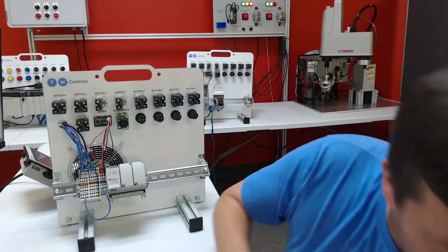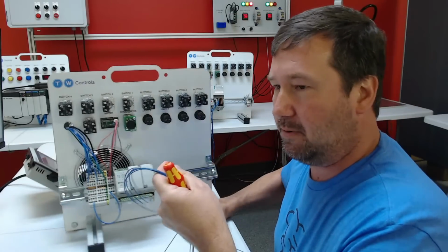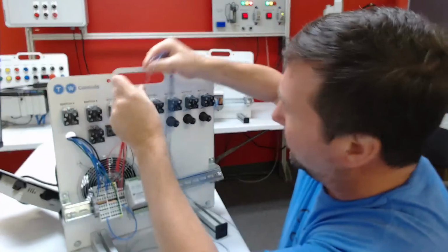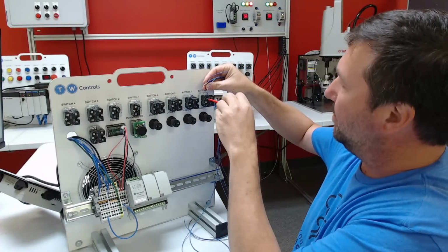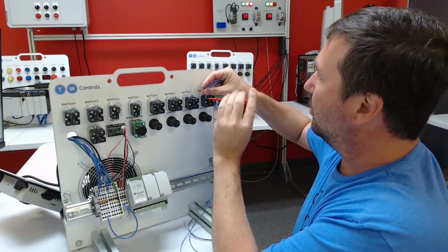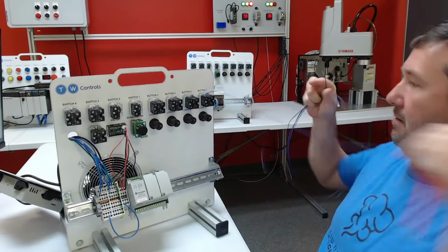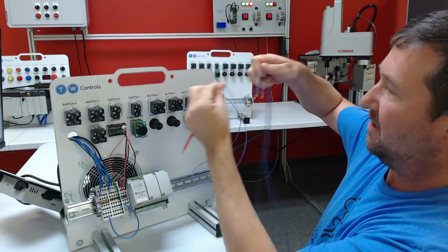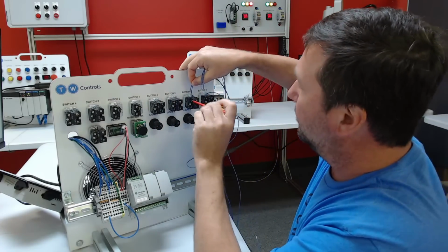So I'm going to grab some wire and go ahead and hook up just these jumper wires. I'm going to jumper, well actually not all, we're going to go from switch 1 through button 1. And this is going to be the green contacts. That's going to be our normally open contacts. So I have one wire in the first one, and I'll take that wire and another wire and I'll put it into button 2.